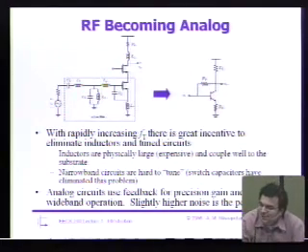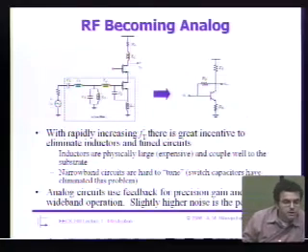Yeah, you can also have cross-coupling between the different inductors. That's also a very good point. Because these inductors are physically large, they easily inject signals into the substrate and also capture signals from the substrate. And the same for stray magnetic fields. So if you're building a complicated IC and it has 20 of these inductors, and one of the inductors is in the power amplifier, another one's in the VCO, you better be worried about the coupling that's going to happen between that power amplifier and that VCO.